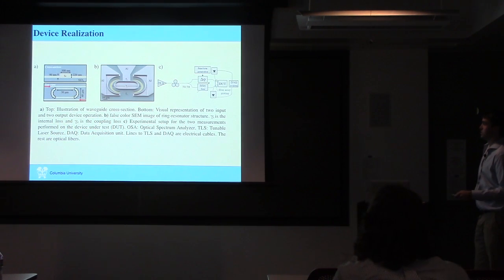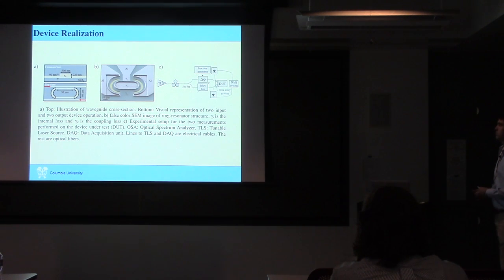And this is a little schematic to show you. So we use these dimensions, just 500 nanometers, to ensure we're in single mode operation. And we used this size, so our free spectral range was about 4 nanometers, so our resonances are about 4 nanometers apart. So we could show that it could do WDM, things like that.